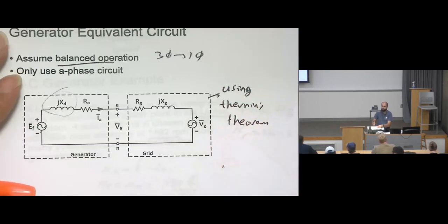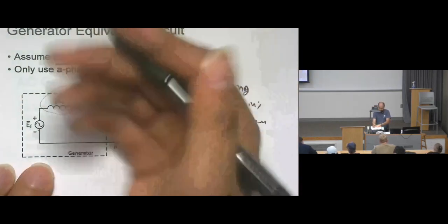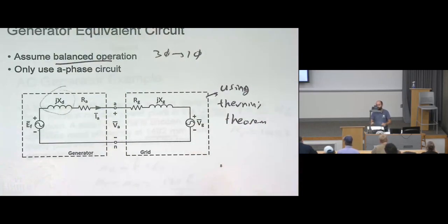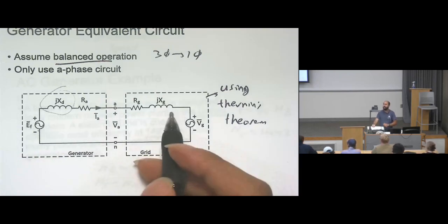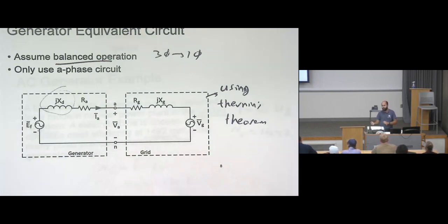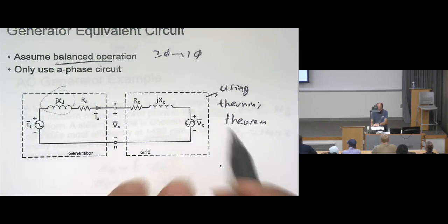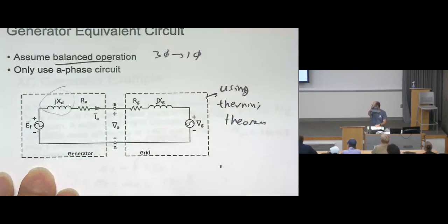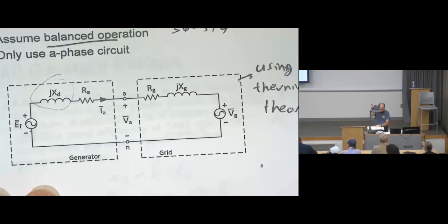So we see that Thevenin's theorem is also very important for us. This is the generator, inside the generator, and here is the grid using Thevenin. The grid, of course, is more complicated than that, but we make it a shortcut, as a voltage source and resistors, and impedance. In AC, it will be impedance instead of resistor. It's only a single loop, but we can make a shortcut.